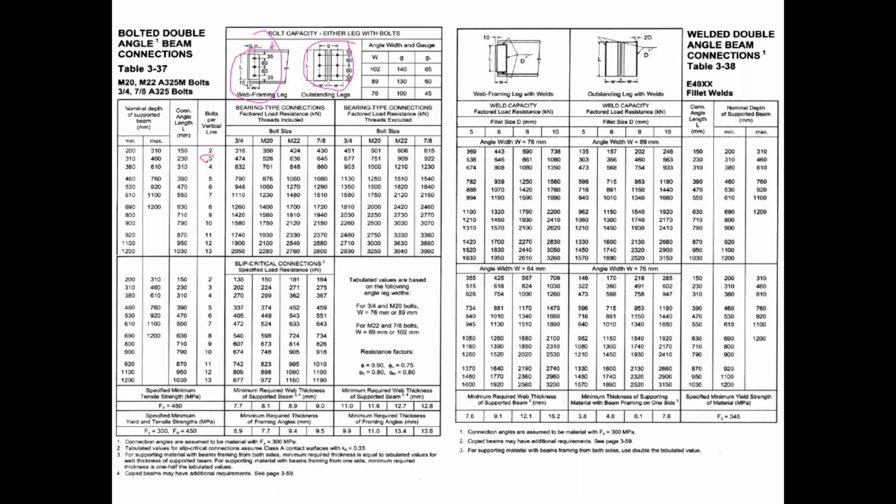So here, for example, let's look at this line here. Let's look at 3 bolts because that's what you see in the diagram. Here they're just showing you graphically where the bolts are located, so people can graphically relate to the number of bolts. Here I have 3 bolts this way, I have a VR value of 474.4. Here I have 6 bolts this way, and I have a VR value of 474.4. So I have the same VR value because both diagrams apply to this table, because the same amount of bolts on a vertical line.